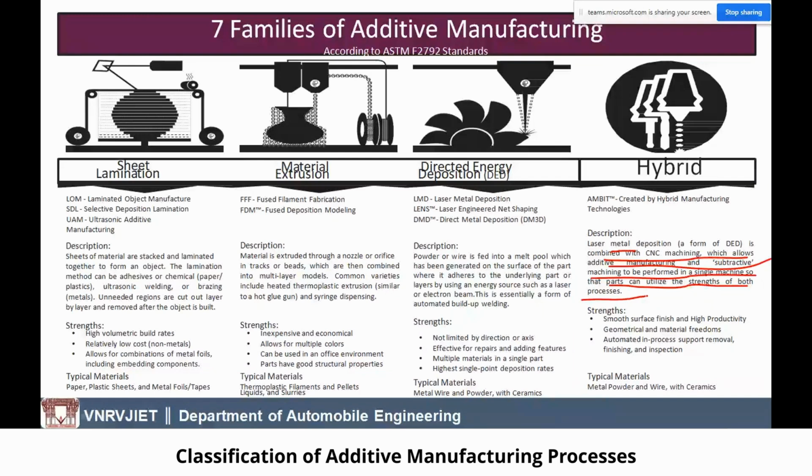So this is the layer droplets it is depositing, but on the backside there are two more tool holders, and here you can assume this is a drilling process, and this you can assume as a milling process, and here the additive manufacturing process. So combinedly we call it the hybrid manufacturing process.